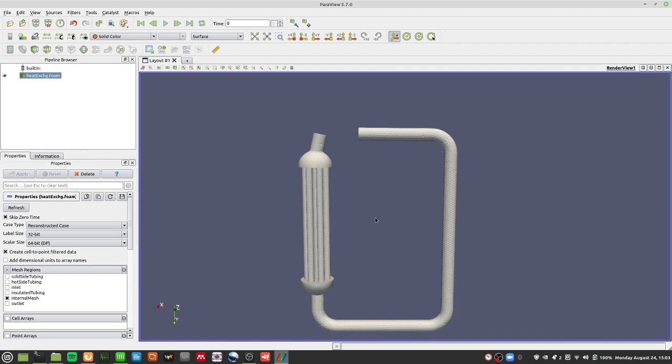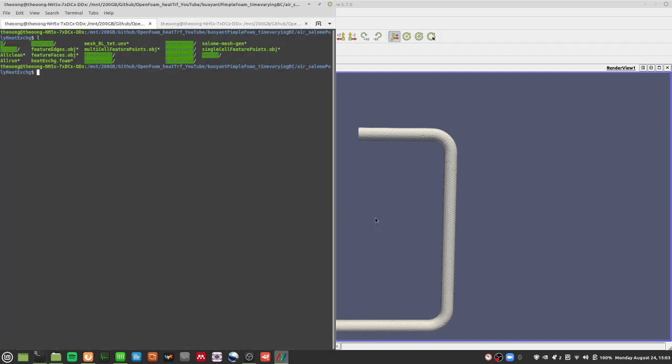Now how do you visualize what's going on? Basically you want to make your time steps small enough so that you can see the velocity fluctuations and whether it's going out of bounds. You also want to take a look at the temperature, because as you saw just now, the temperature also went negative.